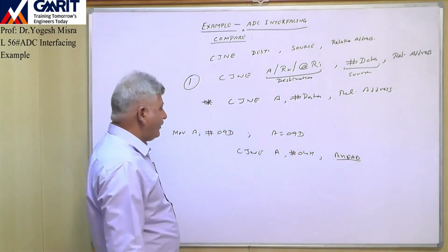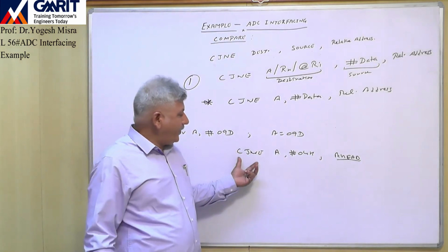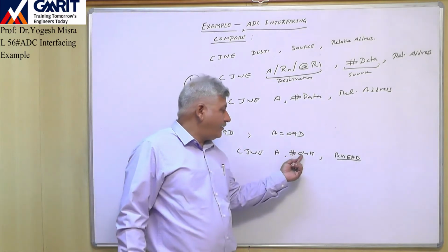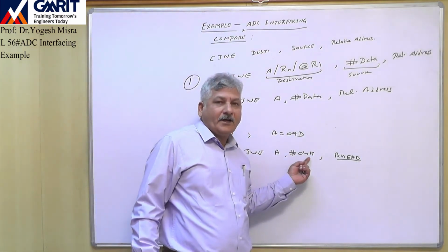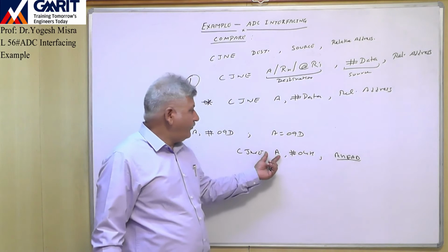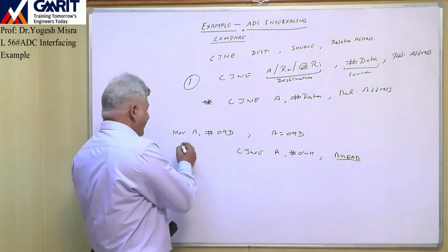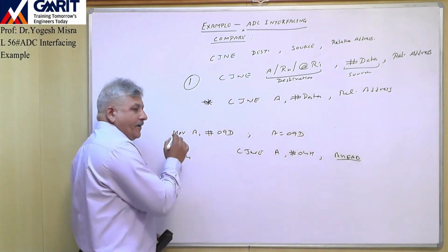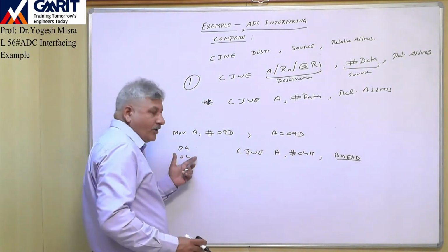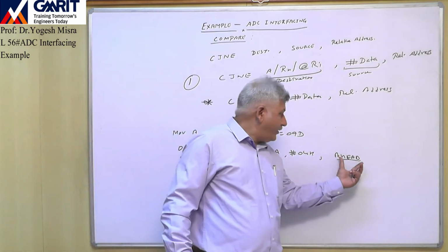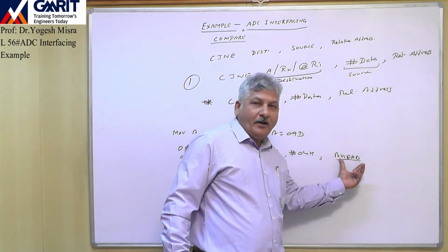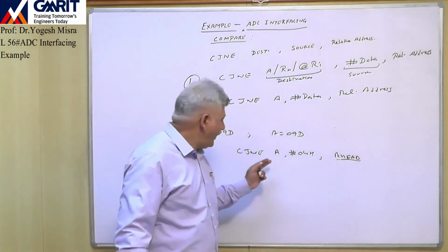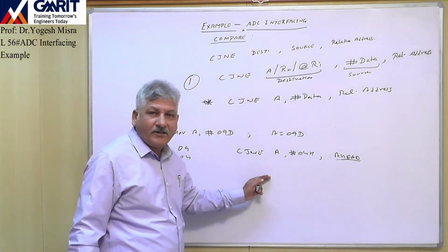Like this. So now with this instruction what will happen? The content of A will be compared with 04. This is the data now. In A we have 09. So basically 09 and 04 are compared. If these numbers are not equal, then go to the label ahead. And if the numbers are equal, then don't go to the ahead label; execute the instructions written after CJNE.